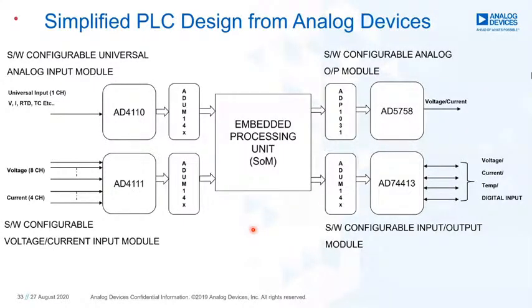Second, the linearity degrades over time because of the CTR ratio. That brings in a lot of disadvantage when it's a closed loop system, or rather in highly accurate systems. So the idea is to avoid this kind of non-linearity and bulkiness when you want to isolate the signal.